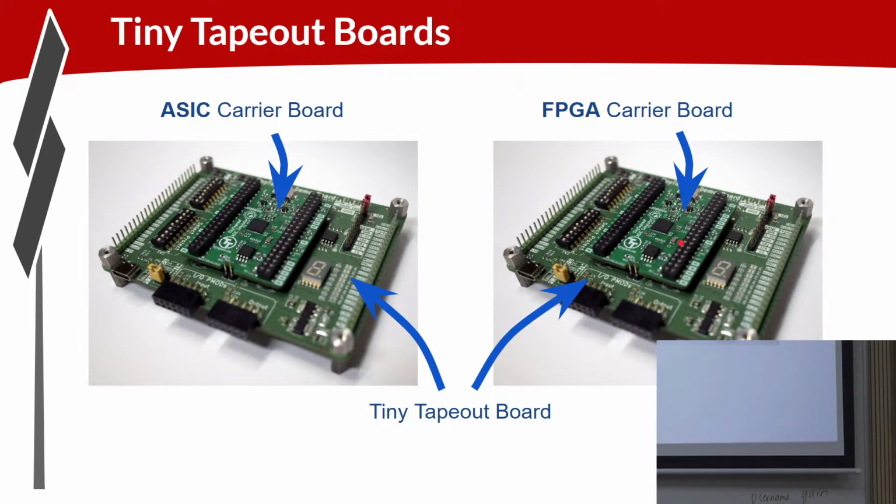It works out quite nicely because the FPGA logic will be larger and take more area, but in the FPGA case, it's just your project that you're putting on the FPGA, right? Whereas in the ASIC case, you're squeezing your logic in with a whole bunch of other projects. So generally, if your logic is going to work in the ASIC flow, it'll fit in the FPGA without any issue.